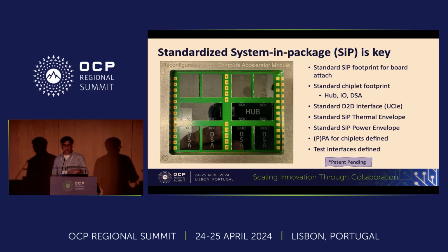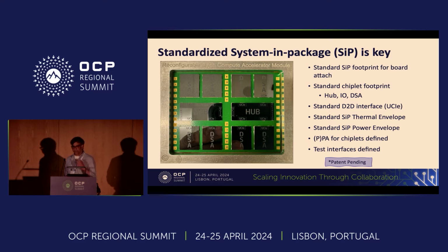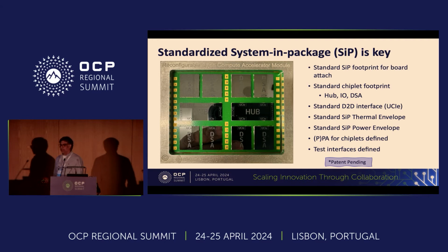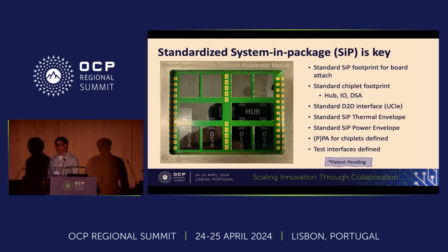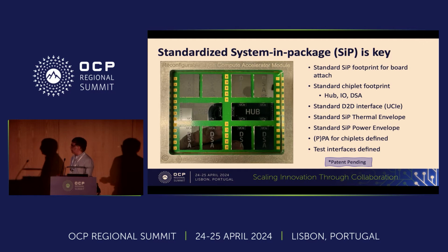which could be PCIe or 112G. And this would match whatever is part of the UBB spec. In this case, its total bandwidth is about 2 terabits, either with a by 16, that depends on whether you're Gen 5 or Gen 6. And then all of the domain-specific accelerators are connected through UCI die-to-die, anywhere from 2 to 4 terabits of bandwidth die-to-die.